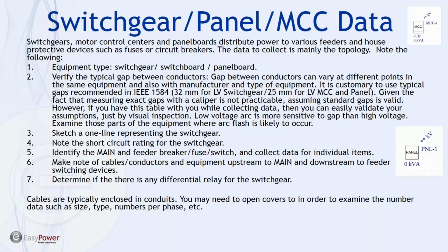Switchgears, panels, and MCCs, again, anytime there's a potential for an arc in an enclosed box or enclosed area, you actually have an amplified radiation, and generally if you're looking in or working through the only opening in that box, all the energy from the arc will be radiated out the opening, and so it amplifies the harmful effects of an arc flash.